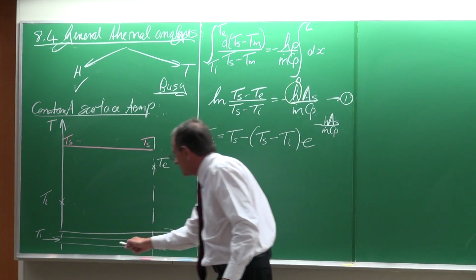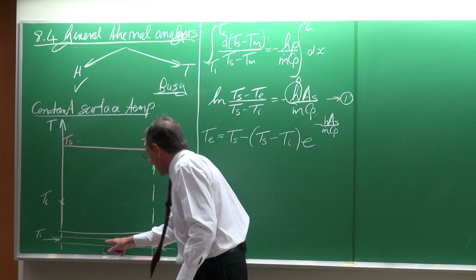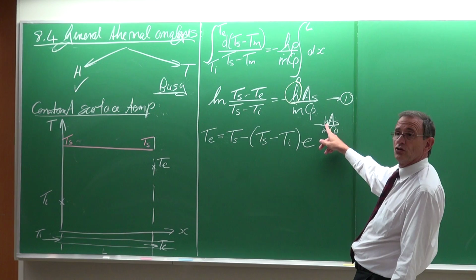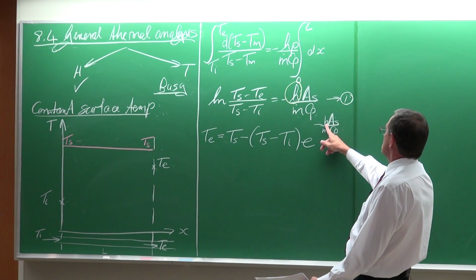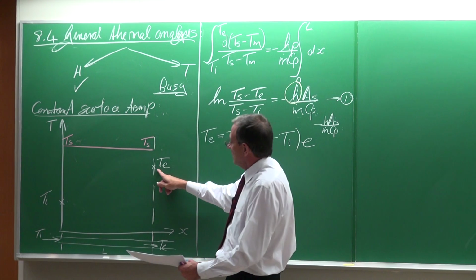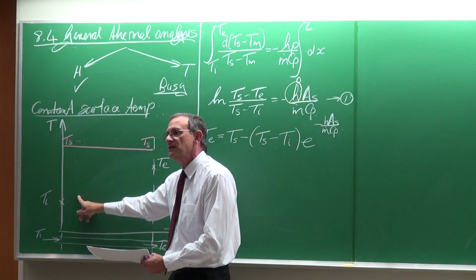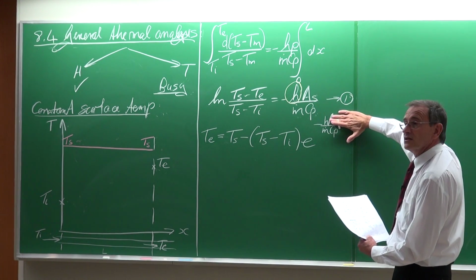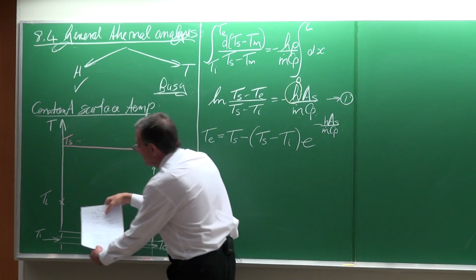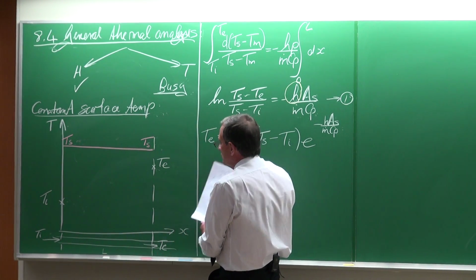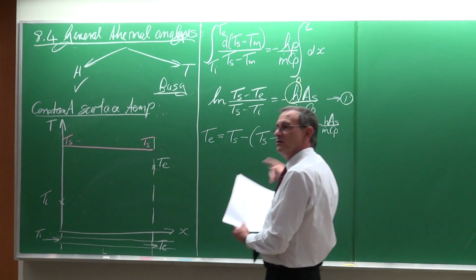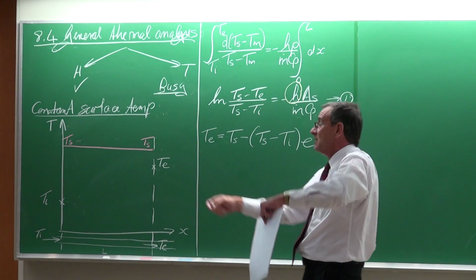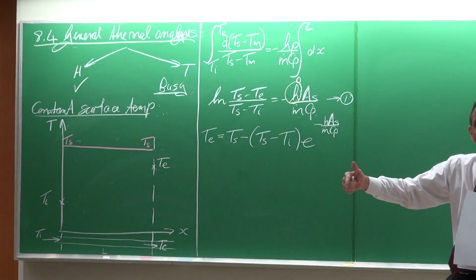So if you now think of this length L, and you've got the diameter, then you can go and calculate that outlet temperature if you've got the average heat transfer coefficient. The question, however, is, yes, okay, that is now great that we can do that, but what would the temperature be here, or what would it be there? Okay, so if you just imagine that this area is obviously dependent on the length. If this was for 5 meters, you can calculate it, but you can go and do the same calculation just for a 1 meter length. So this area you can write in terms of x.